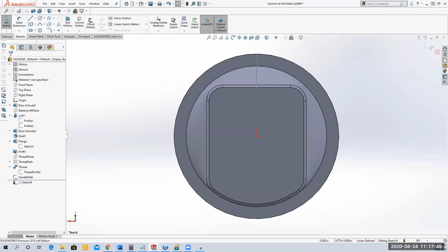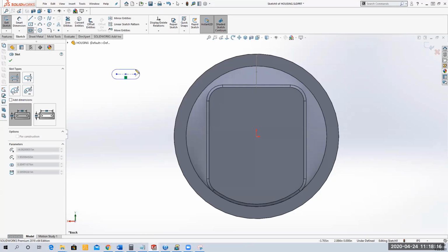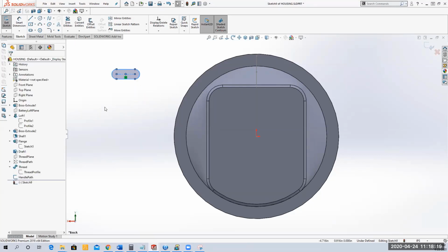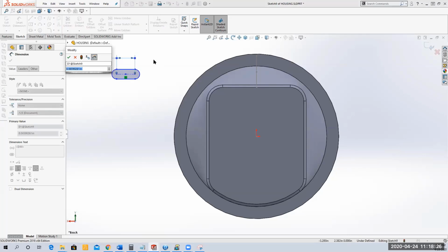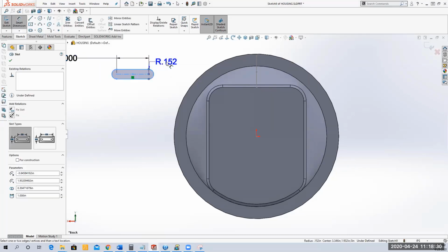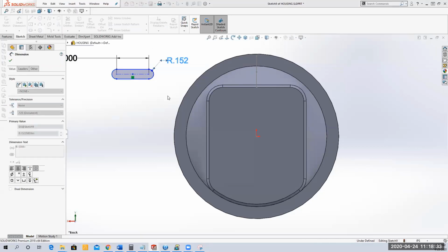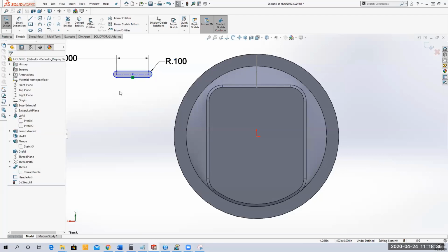And then instead of drawing it the convoluted way she says, I'm going to use this slot tool. Okay. And I want to create the slot that you see on the bottom of page 6-50, using the slot. Okay. So I select the slot tool. I'm just going to draw a straight line and then come out. There's my slot. Okay. And this is going to have a dimension of 1 inch. This is going to have a radius of 0.1. So I've drawn the slot.